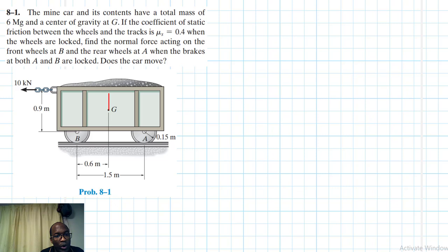So we have the weight acting through the center of gravity G. And then we have the reaction, the normal force, and also there the normal force. Then we have friction. Friction always resists the movement of two contacting surfaces that move or slide relative to each other. So this direction cannot change as long as the force is in the direction shown.